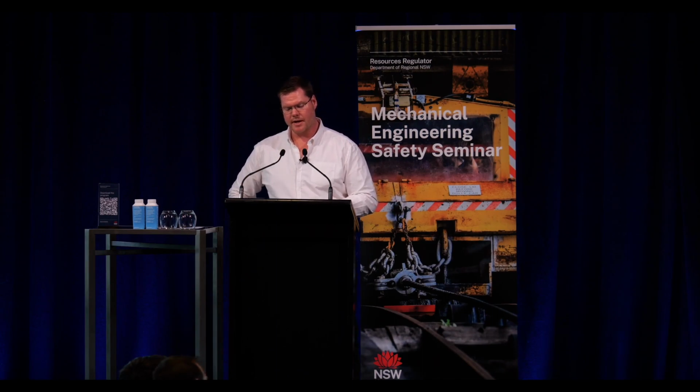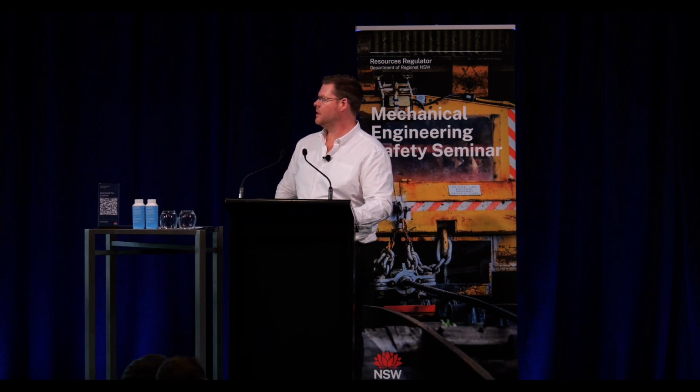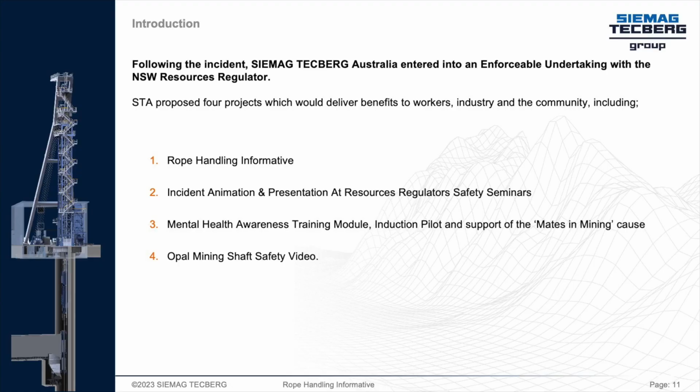We increased the barricading zone. We installed CCTV monitoring systems, so we didn't have to have people as close to the winch rope for the removal or the installation, and it also gave the operators of the winders and the winches better picture and understanding of what's happening around the area. We also installed set point monitoring to measure motor current to limit the capacity of the winder.